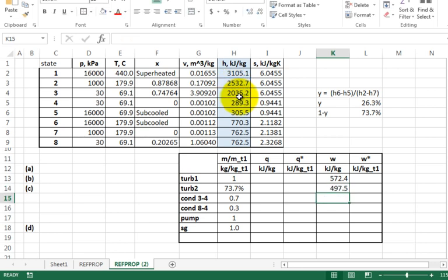Enter. But now I want to use this mass flow rate. So it's equal to what is here times right there. And it says, well, that didn't do much for me. But for the next one, it does, because for every kilogram that goes through the first turbine, I get only 366.9 kilojoules of work out of the second turbine. Make sense? Good.